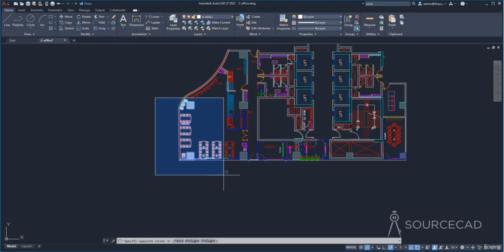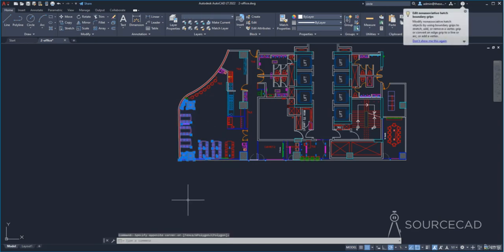If however you move it kind of like this, then it will select everything which is completely inside. But look at these two objects. These two objects are not selected because they are partially inside and partially outside. So everything should be completely inside for this selection to work. Now I'll click and everything which was completely inside the window is selected.